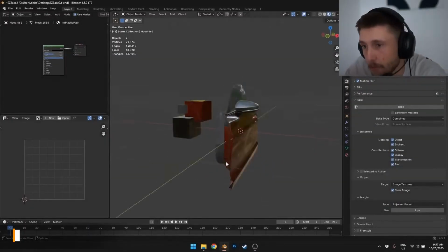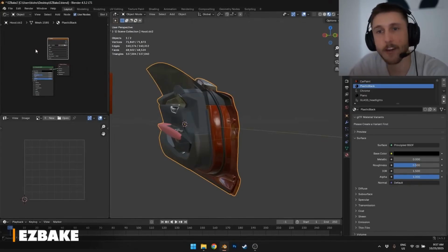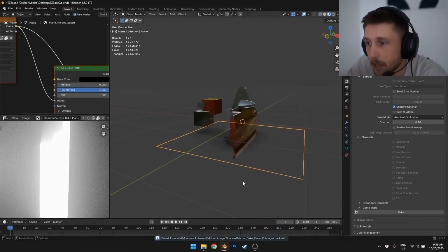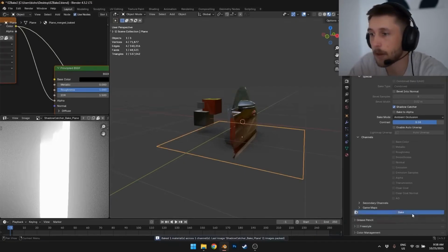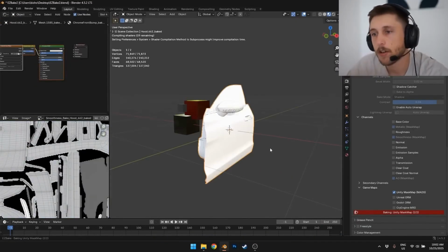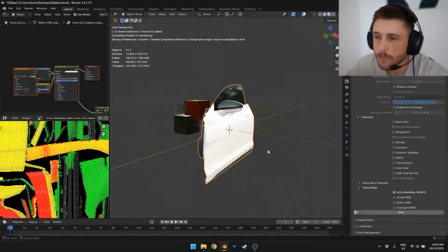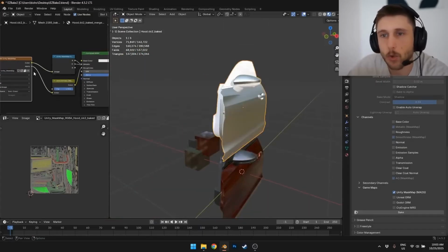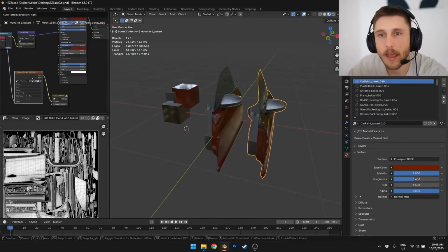The highly tedious process of texture data compilation is brilliantly streamlined through the Ezbake framework. Designed as a dedicated automated baking solution, the underlying engine calculates the data points of any three-dimensional mesh utilizing standard principled BSDF material attributes and autonomously generates precisely mapped physically based rendering textures.